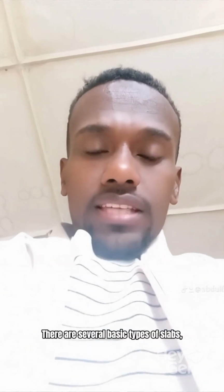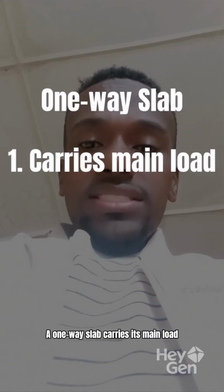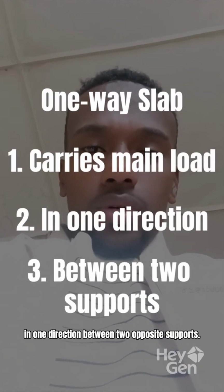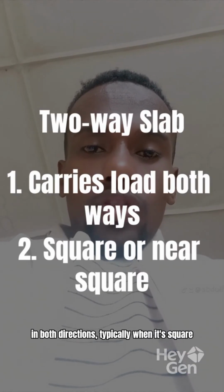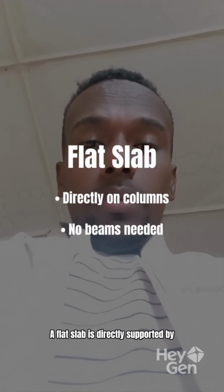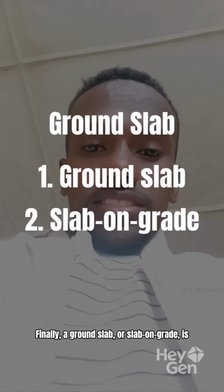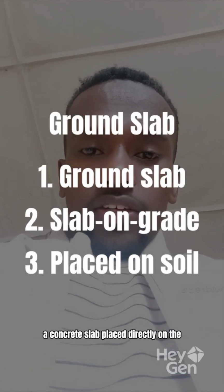There are several basic types of slabs, each serving a specific purpose. A one-way slab carries its main load in one direction between two opposite supports. In contrast, a two-way slab carries load in both directions, typically when it's square or close to square. A flat slab is directly supported by columns without the need for beams. Finally, a ground slab, or slab on grade, is a concrete slab placed directly on the soil.